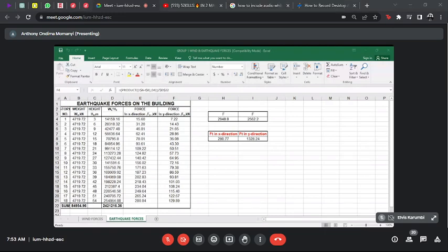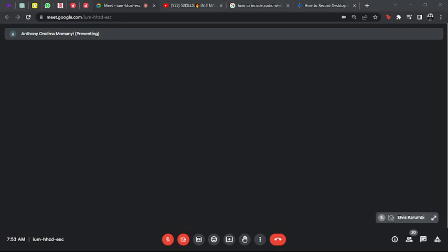Thank you. I can allow one of my members to present what we have done on the model. Okay. A question before you move on. In the calculation of the force for the top floor, the formula was 0.004 F into the height of the building over Ds squared, and this Ds is the plan dimension of the lateral structural system resisting earthquake forces at the ground floor. My question is, how do we get the Ds? How do we calculate the plan dimension for the lateral structural system resisting the earthquake force at ground level?